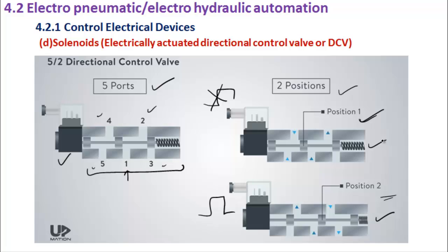The spool is in such a position that the spring is basically expanded, and now the power is going from here to here and the return is coming from here to here. That is the first position.